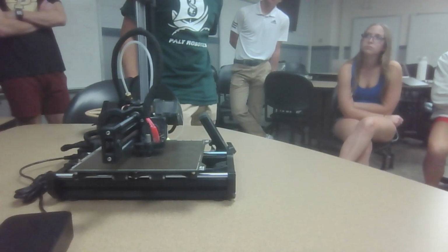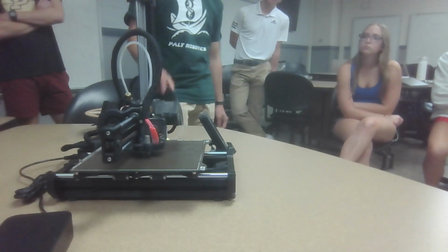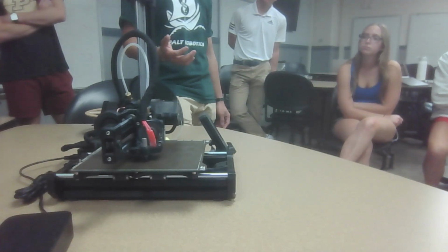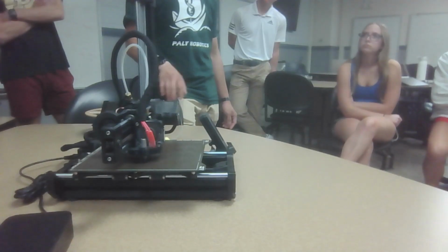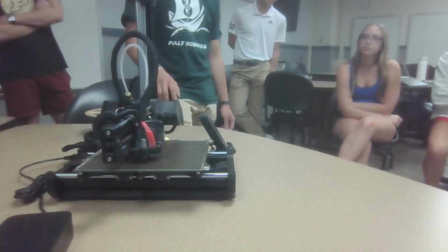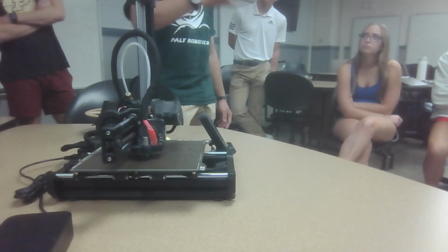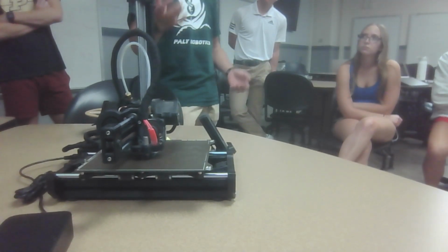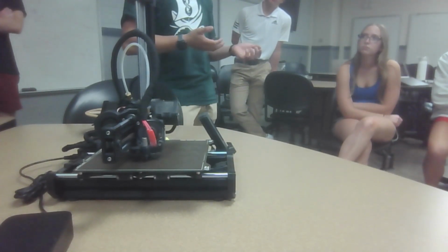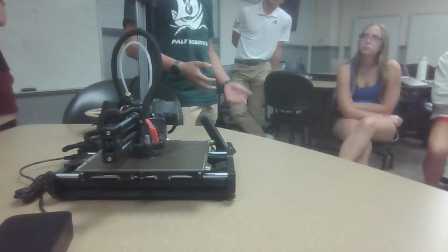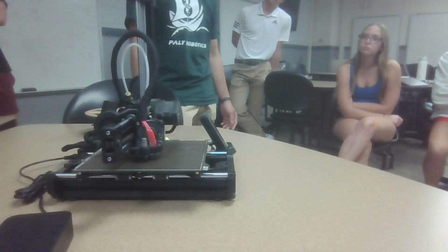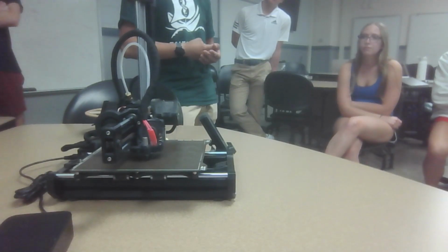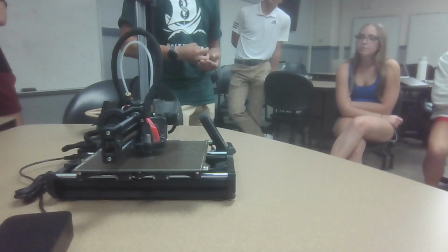I guess this is kind of being a bit technical, but input shaper is kind of an up and coming thing for a lot of printers. It basically is resonance compensation, right? When a printer moves around, it will vibrate a little bit, and depending on the mass of all the parts, it will resonate at a certain frequency, and input shaping can compensate for that. So it allows you to print faster without any visual defects. If that makes sense. It's kind of complex, but it's really cool.